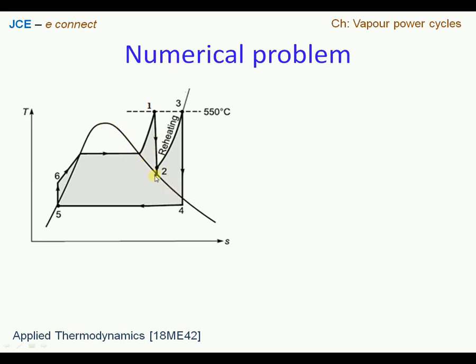So that means we don't know the intermediate pressure, but we know that the entropy at state point 2 is closer to the saturated vapor region. Therefore we have to search the table holding the value of S2, where S2 is equal to S1, and see where exactly it coincides. At that coincident point, once we refer to the pressure column, we will get the required intermediate pressure, which is called the reheat pressure.